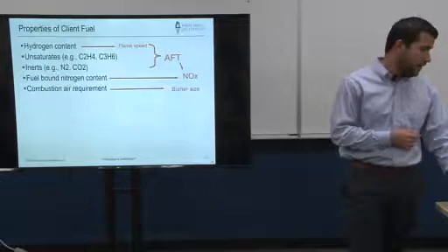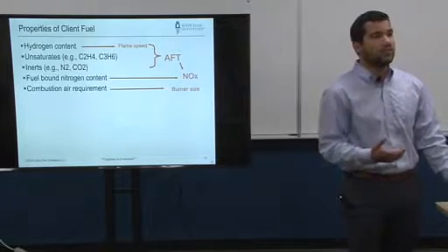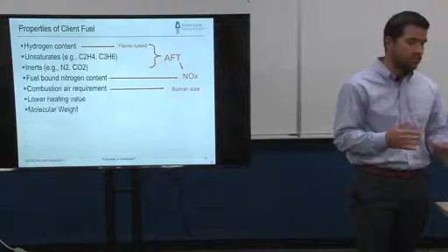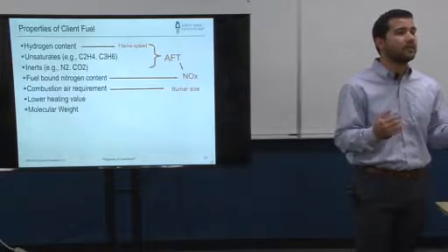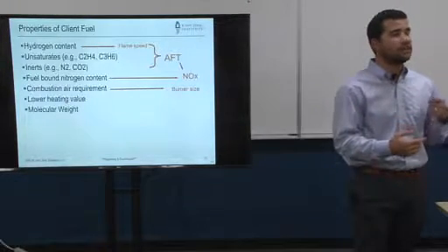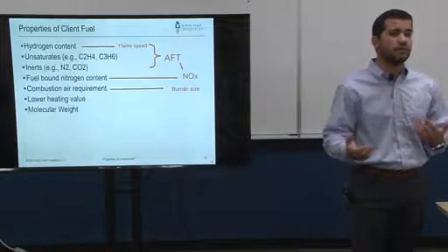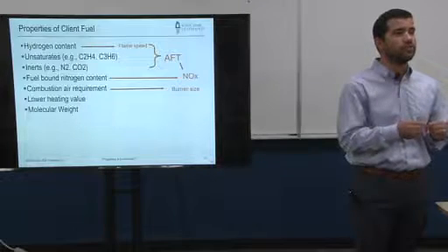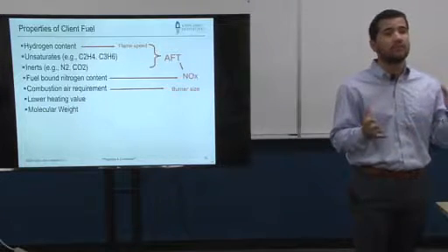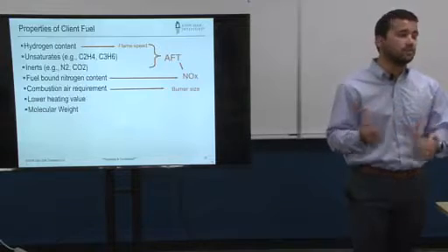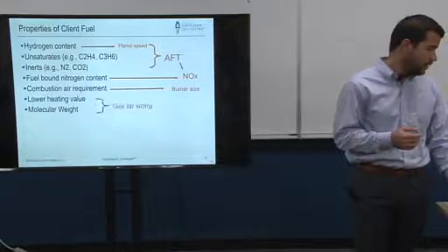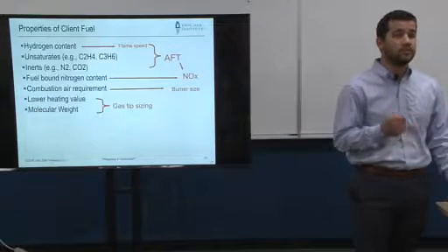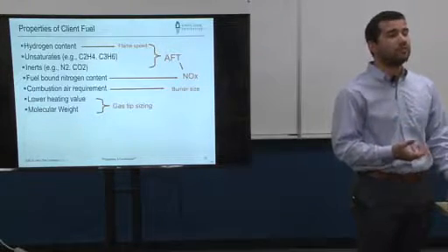And finally, we have the combustion air requirement, just how much air you need to combust the heat release that you have, and that really comes with the burner design. So you size your burner accordingly. Typically, when you're doing a test, you specify the burner pressure drop. If you will, it's essentially the amount of energy, the amount of pressure that you need to get a given volume of air through a geometry. And finally, we use the heating value and the molecular weight of the fuel for gas tip sizing, because they also tell you what pressure you have available on site.